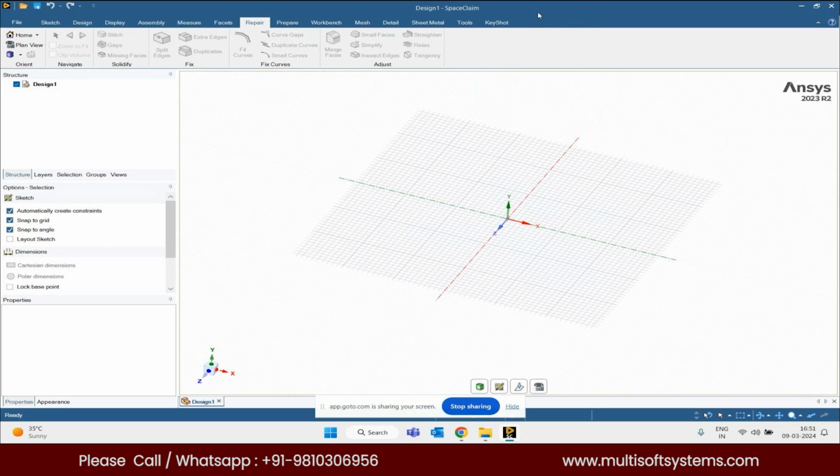If you go with a very bad quality of geometry, then it will increase our efforts in the meshing. So one should be very aware that if it is a bad CAD, one should make conscious efforts to make it clean and a good CAD, a watertight geometry, so that a good quality of mesh will be created. It is not that there is no way to proceed with a bad CAD, bad geometry, and work around it in the meshing mode. It will take a lot of effort.